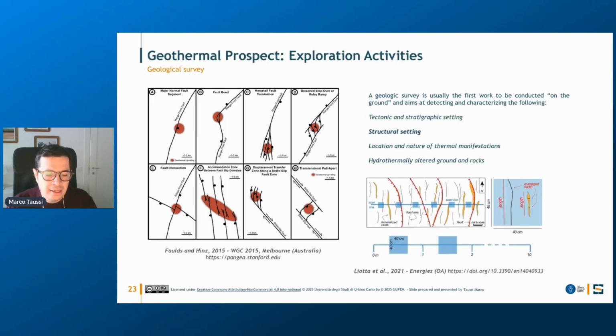We make these interpretations precisely through surveys, aided by the satellite images discussed above, but also through geomechanical analysis. The geomechanical survey on the ground, where we can gather information related to the opening of the fractures, the distance, the spacing, and therefore the persistence of the fractures themselves, the immersion, the position. In short, all those characteristics we could use, which we could also exploit to interpret rock's permeability value, a fundamental parameter in identifying reservoir rocks.